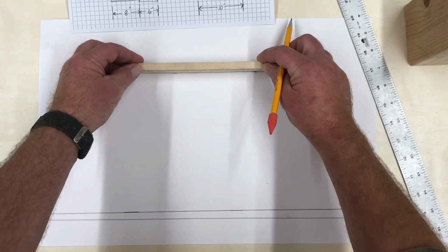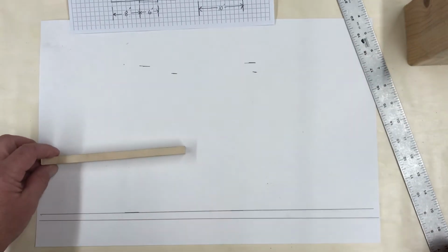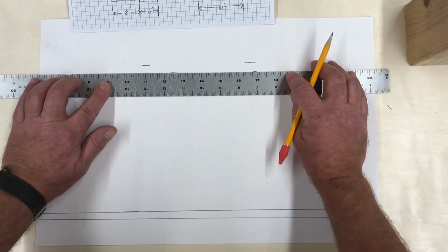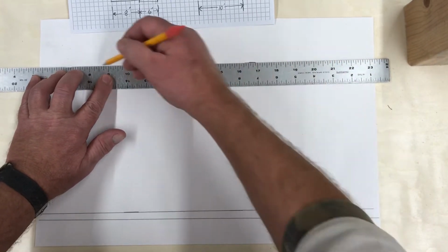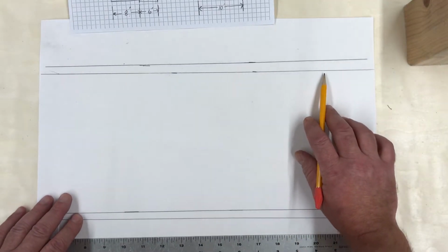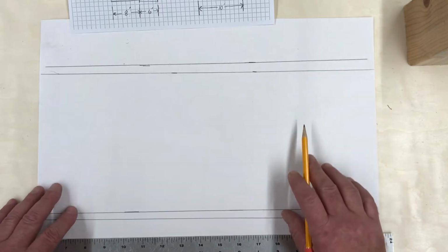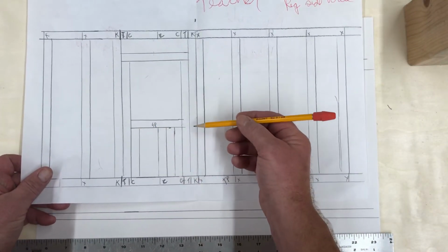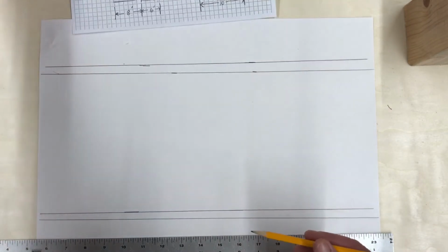Now, we also have the thickness of the top plate that we need to put in, and that is, once again, 3/8. So we're going to come up here and draw this plate. Now we have the thickness of the plate. Once again, I'm not really grading on whether the line is drawn exactly straight. What I'm grading on is how you place the members of your window. Make sure that you draw it correctly because you will be building it the same way.